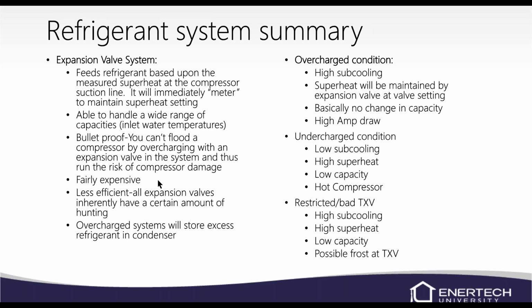I guess they're fairly expensive. The expensive part, I guess, is installing them. If you don't have to change your expansion valve, we definitely don't want to, because we got to break into that refrigerant circuit. So it's kind of an expensive repair, and a lot of times, again, the TXV gets blamed for things it's not really its fault.